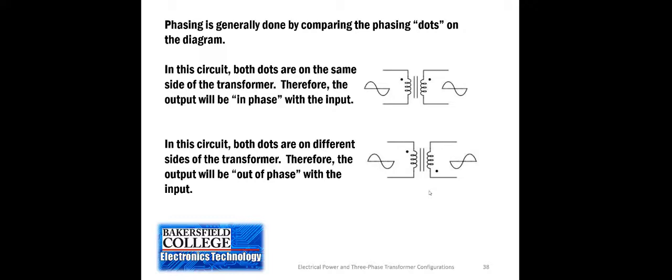And you're not going to get the same voltage if you measure between 1 and 3. So that phasing is vital. Generally, when they build the transformer, it's pre-wired so that the phasing is correct. But if you're connecting three individual transformers to make a three-phase assembly, then you have to be careful which is the correct phase and to connect them together properly.